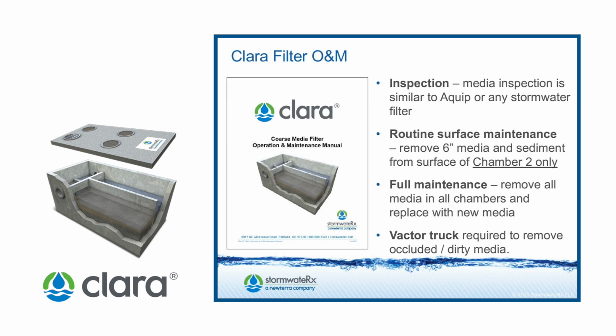The routine maintenance removes and replaces approximately 6 inches of inert media from chamber 2 only. This activity removes the sediment buildup that was captured on top of the media and will help reestablish the filter's flow capacity. A full maintenance requires both filtration chambers to be completely cleaned out of the inert media and reloaded with new media. This activity will establish the filter's full flow capacity, almost as if it were like new.